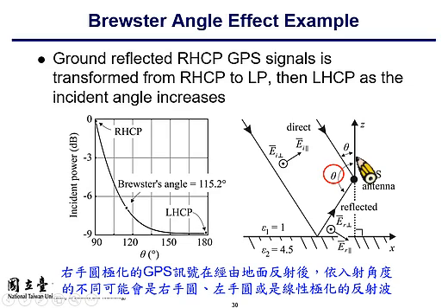The incident angle defined here is this theta angle. So that should be put into different signs. In terms of GPS signal, we know that the GPS signal is right-hand circularly polarized. So if you want to receive the GPS signal, you should have a right-hand circularly polarized antenna facing upward.